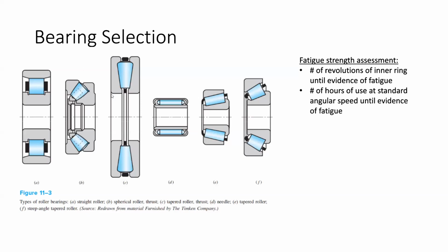So these different bearings are all solutions to kind of solve this problem. And the way I like to think about bearings is from a pressure on each individual roller element standpoint. If we look at this first example, you can see that the line of contact between the cylindrical bearing rolling element and the two shells is a line, right? You have a straight surface here, but this roller is of a smaller radius, so it only contacts in a line. So what happens when you have a stress on a purely line element? It's infinite because the line has no area.